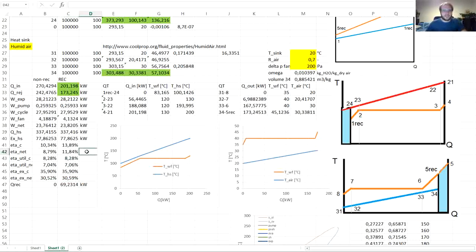So you can see that adding a recuperator into our system increases the efficiency of the cycle, but in case of waste heat recovery, it does not increase the work output or the network output, or only very negligibly. So for this reason, unless you have some limitation on the temperature of the heat source outlet, for example due to some precipitation of minerals in geothermal applications or condensation of flue gases in application to some gaseous waste heat, adding a recuperator into such systems is generally not justified.